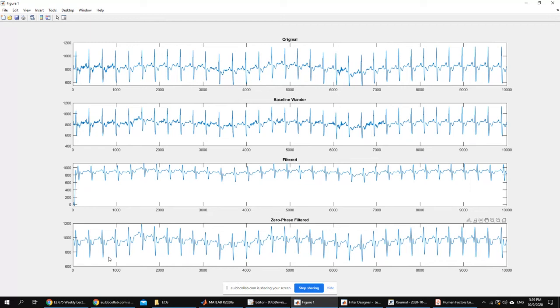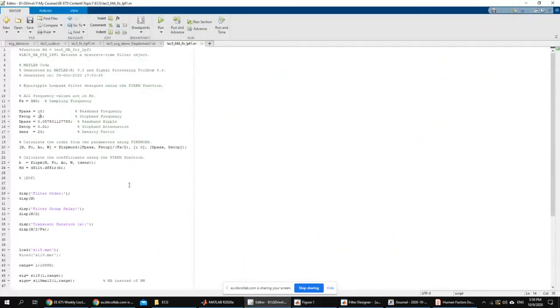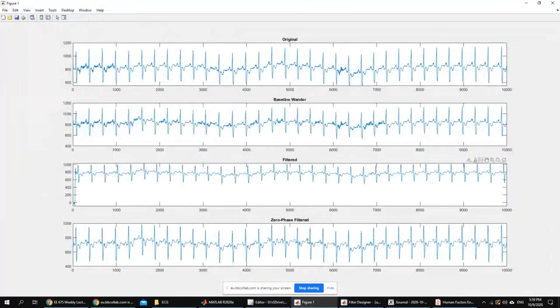Okay? If you take it further than that, to the point where the ECG signal doesn't look like an ECG signal, then you will have a problem. Okay, so the previous result, the one that we had before, was actually not bad. It looks okay. The ECG signal looks okay. The artifact here looks a little bit reduced. So basically, if you compare this to this, definitely it's reduced. The first 3 cycles here, definitely it's reduced. So this is a kind of optimization I want you to do.